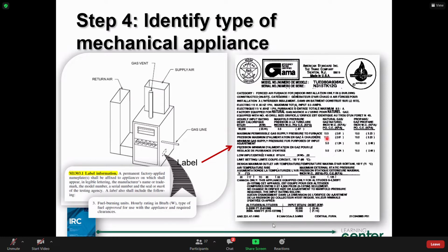Now that begs the question, right, Doug? How am I going to measure that? Well, I'm going to measure that right at the gas valve in the furnace. There's usually a port inside the gas valve, like an 1/8 inch female pipe thread, that you put a barb on and put your hose on. You can measure the gas pressure right at the gas valve for the gas supply coming into the furnace. That's one way to measure it. If it's propane, which this furnace has the ability to be converted to, 13 inches water column is the maximum pressure permitted.